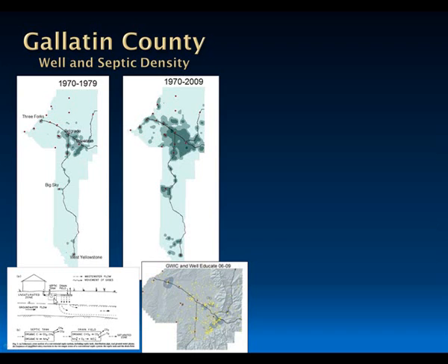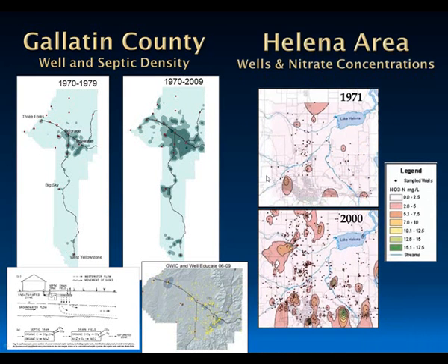They have primary treatment in the septic tank, and then they rely on treatment in soil to remove a lot of the remaining constituents. Traditional septic systems are not designed to remove nitrate, actually. They rely on dilution in groundwater for that, and that's why they have a mixing zone associated with them. When you get really high concentrations of septic systems, that dilution doesn't always happen.